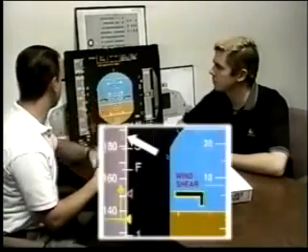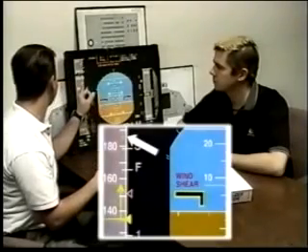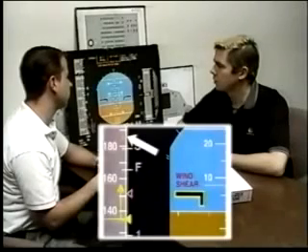On the speed tape, we have an amber tick mark, which we call what? VFE next. Okay. It's sitting at 185 knots, so where are the flaps now? Well, at 185 knots, our next flap setting would have to be 3, so that means our current flap setting would be 2.